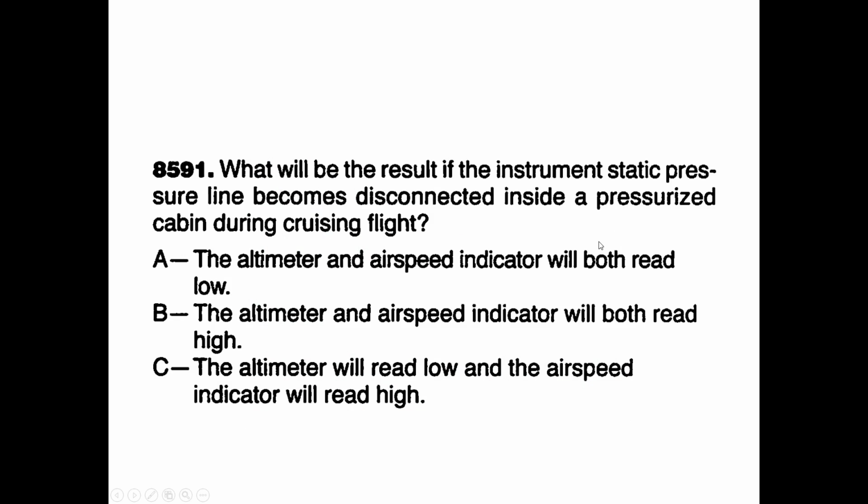Okay, third question. What will be the result if the instrument static pressure line becomes disconnected inside of a pressurized cabin during cruising flight? Well, it's a good thing we took a look at that, because we were talking about reading the pressure in the cabin. It's not really a static port. So this is kind of the same thing. Instead of reading from the static port, it's going to read from inside the cabin.